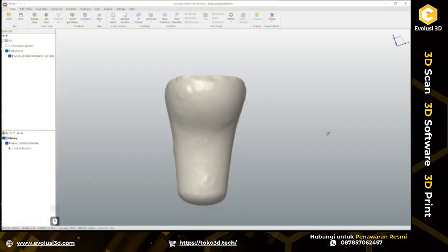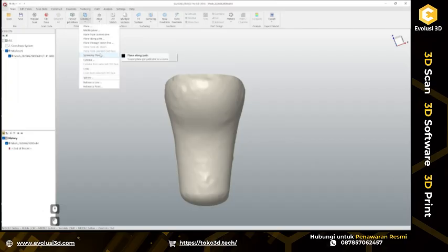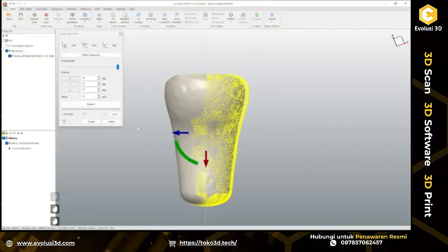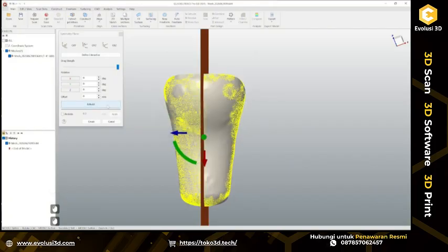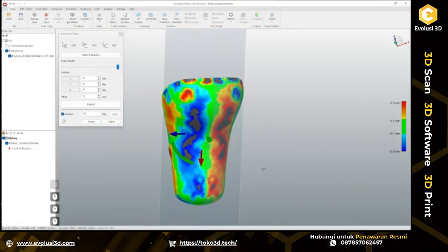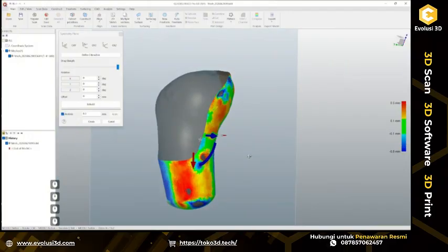Essentially, what's the easiest way to align this object to the coordinate system? In my opinion, we can try to create a symmetry plane and see how it goes. So let's ask the software to rebuild this and propose the best symmetry possible for all of this scan data.